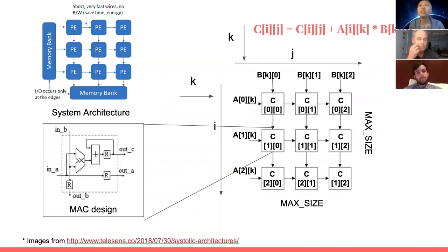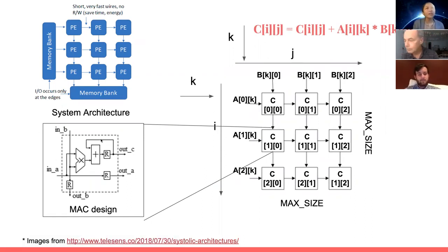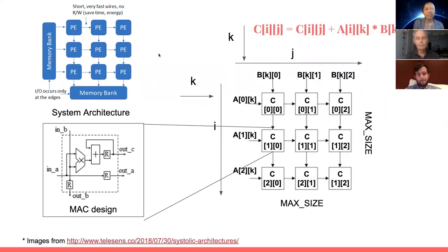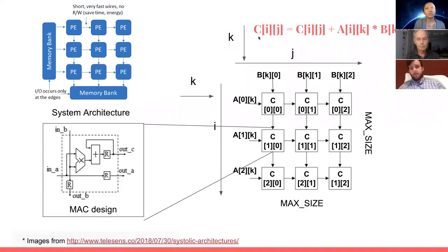So here is a very simple systolic array design. Typically we'll have, so here is just a MAC unit actually. We just connect the multiply accumulation units in a systolic array here. What it does is pretty much compute the output of two matrices. If you see from here, you typically put some on-chip memory buffers at the periphery of this PE array. So this mesh of PEs will be called a systolic array.